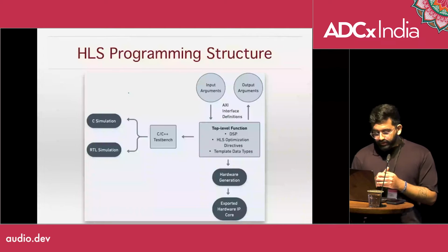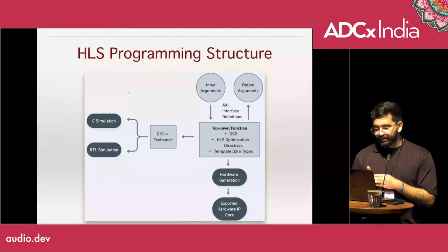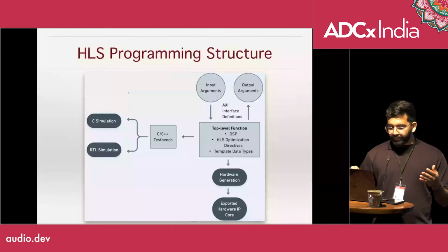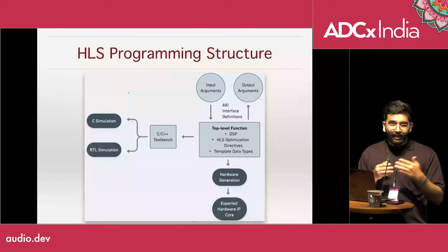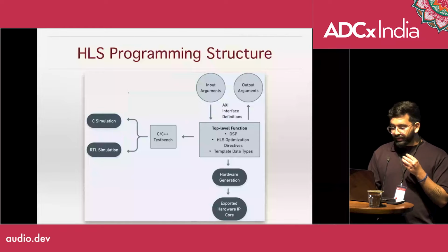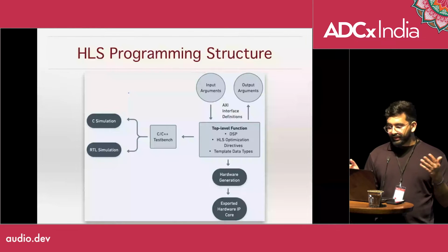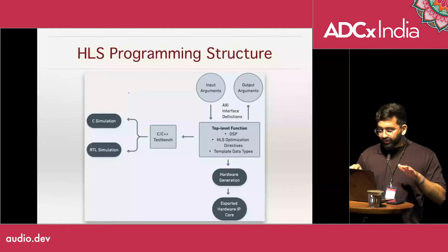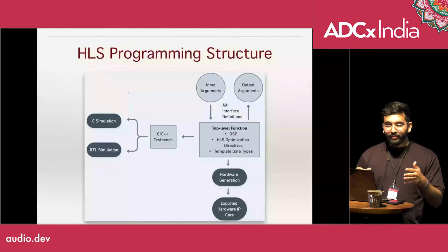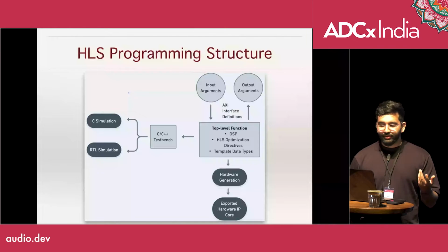Yeah. So just quickly, this is the programming structure for HLS. It's centered around a top-level function, which is what gets converted into a module or IP core that I was talking about. In the top-level function, we put all our DSP, we put HLS optimization directives, and we use very specific data types. I'm not going to get too much into the details of HLS programming. This is more about the structure and the approach and the design considerations.